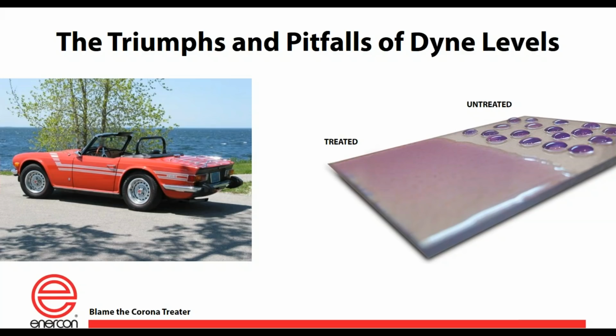Basically, what the Dyne test is doing is giving you an understanding of the surface of the film's ability to wet a liquid. Dyne solutions are made up of two solvents, ratioed in a certain proportion to each other, and that will then allow the solution to be a 36 Dyne, a 38 Dyne, a 30 Dyne, a 50 Dyne, whatever the number is on that bottle.